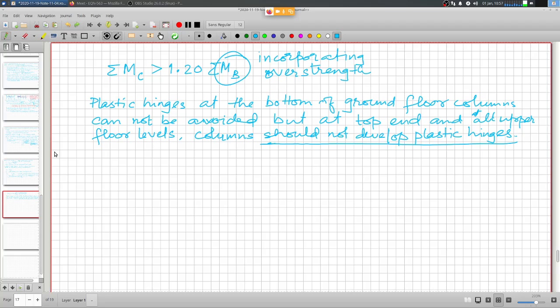They would be transferred as axial forces to the columns, and those have to be accounted for in the interaction diagrams, and the moment capacities for the column should be computed accounting for the axial loads, total axial loads that come onto the system, right?